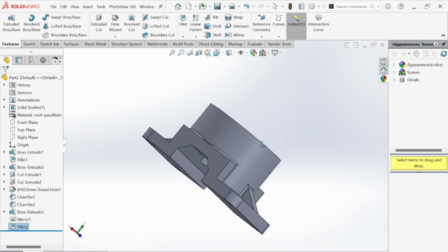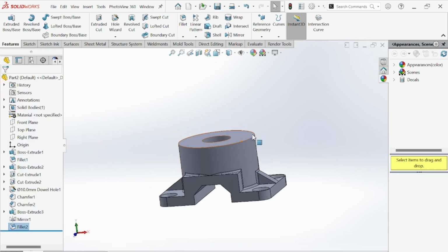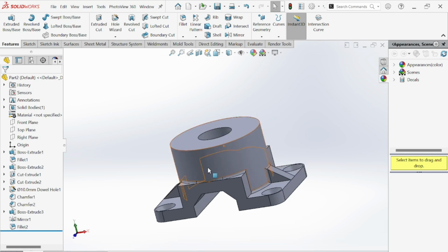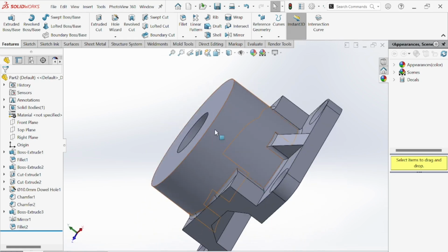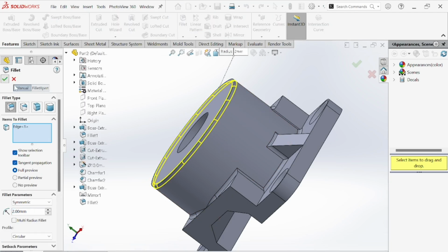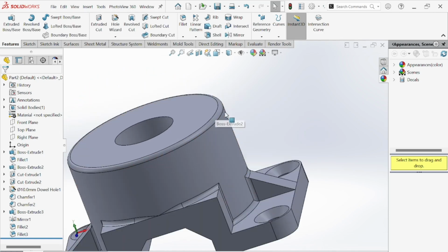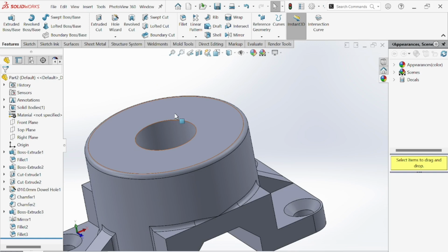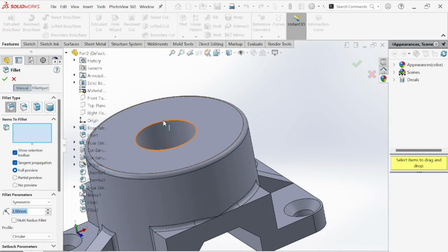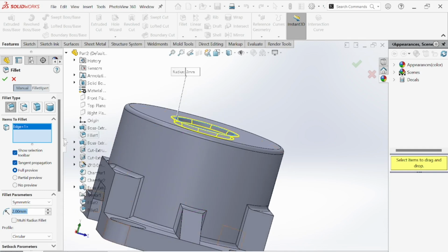Now here you see it's not copied. So now it's perfect. It looks perfect. If you want to make a fillet or chamfer here, you can also do that. Simply click here, go to the fillet. It's 2 mm, and make this one okay. Now here you see it gets a fillet. Now this curvature is called fillet. The chamfer is exactly a plane cut. Now here you see this is how chamfer looks like.